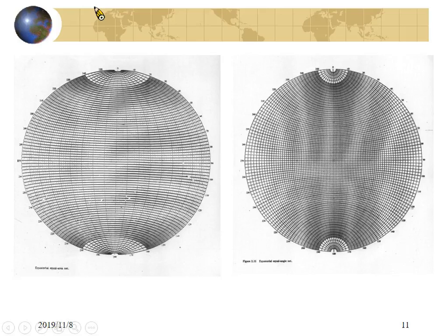But according to a textbook by Hoek and Bray, some geologists told him they insist on using this, otherwise the results will be distorted. But according to Hoek and Bray, no matter this or this, it will not influence the engineering problem too much. So don't worry. For engineers, we frequently use the equal angle projection. That will be this one.